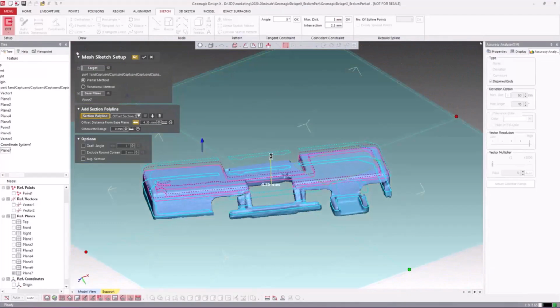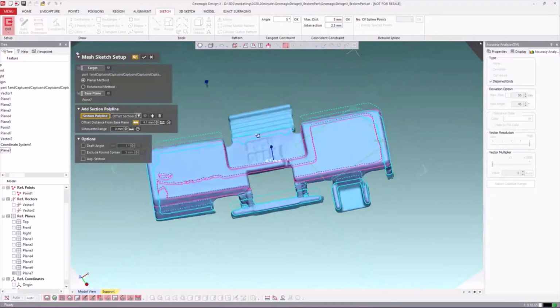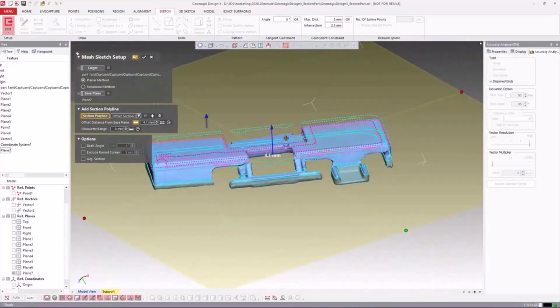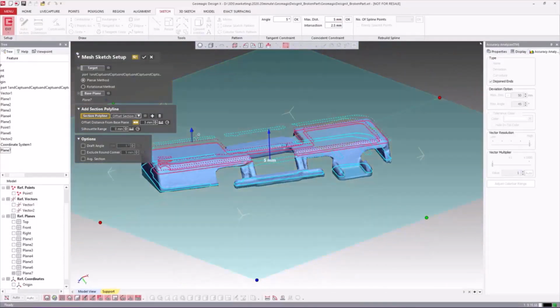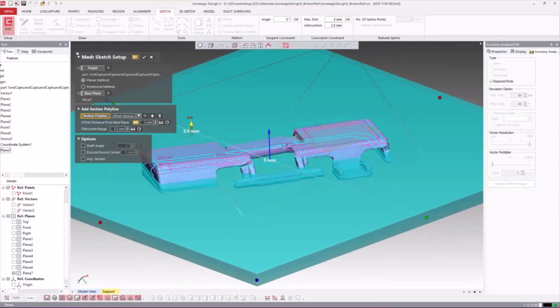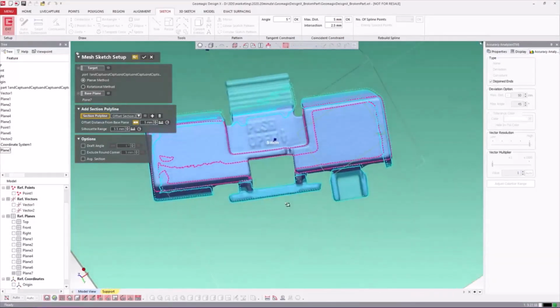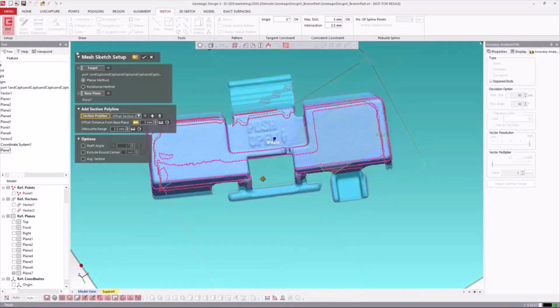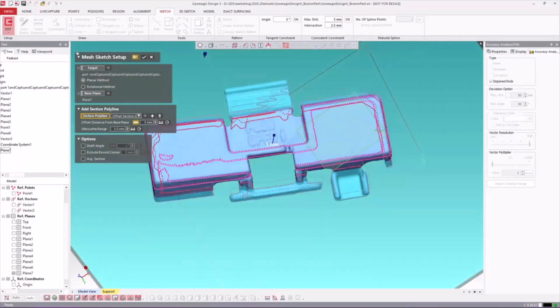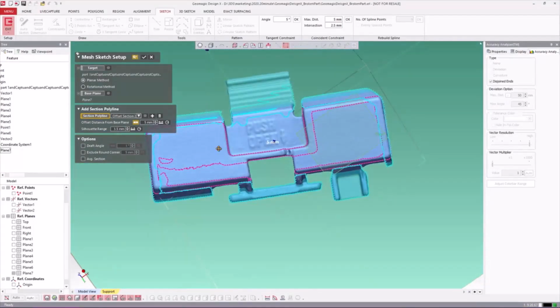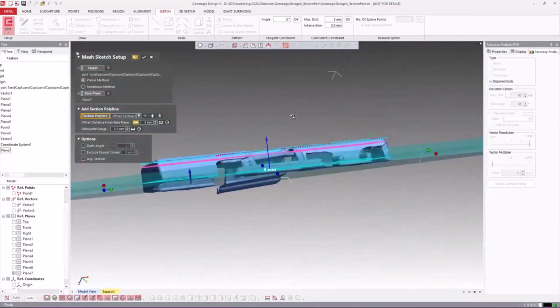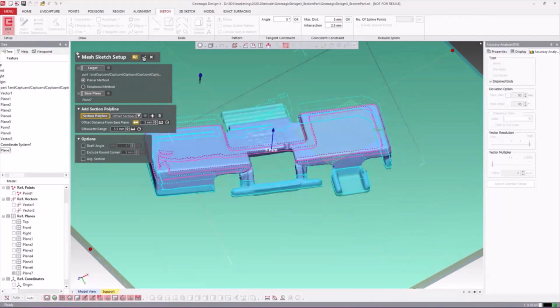And if I really wanted to, I think I'm going to, we already have a nice outline of that box, believe it or not. So I think we're going to leave that there. But I'm going to pull it down here. And just because finding the outer edge of this is hard, I'm going to do a little silhouette here to get the outline of that data. So these we don't really need, but we're mostly just going to look at the outer inner edge of this thing. So I'm going to silhouette that in just to make sure I get the extent of it, and I have it boxed in. So I'm going to hit OK.